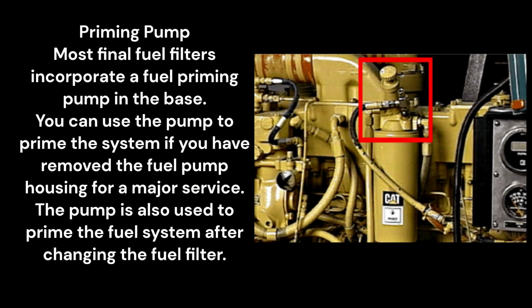Priming pump. Most final fuel filters incorporate a fuel priming pump in the base. You can use the pump to prime the system if you have removed the fuel pump housing for a major service. The pump is also used to prime the fuel system after changing the fuel filter.